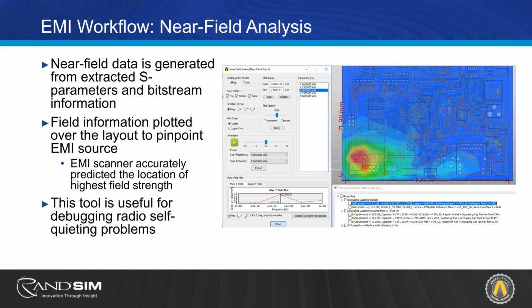Where should I focus the majority of my simulation workflow, like the EMC environment or the full field EMC solver? Yeah, so like I was mentioning previously, the full EMC simulation environment is sort of a last check if you want to do it at all. The majority of your EMC during the design phase should be primarily housed within the EMI scanner and the EMI workflow.